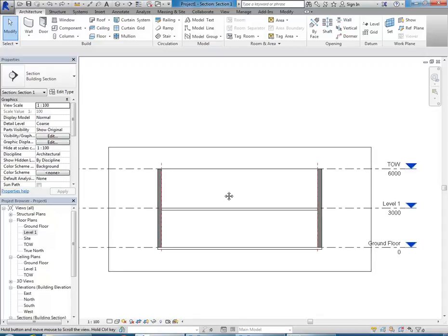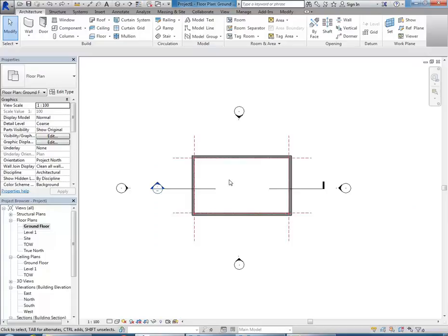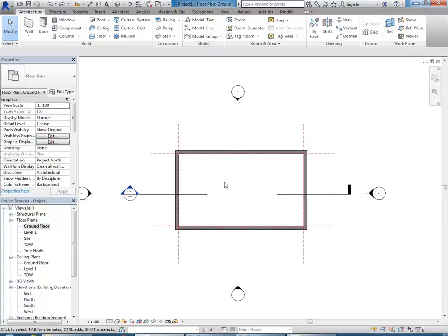Okay, so we've got our levels set up with the main elements, and it's always good practice to think about your spaces in this way, the main walls and the floors, and later the ceilings and maybe the roof as well, to define the overall size of your spaces. And then after you have some of those things set up, especially the walls and the floors, you can come back to putting in the detail and add things like openings.